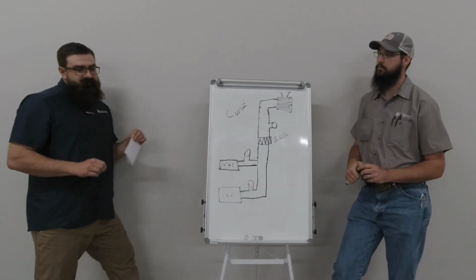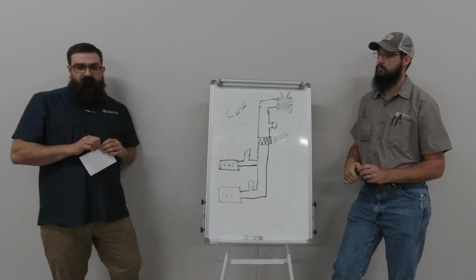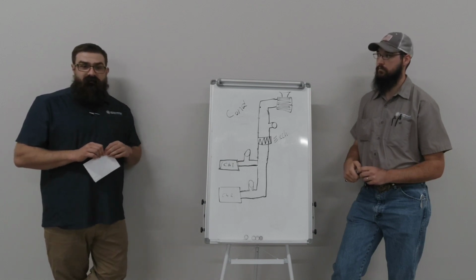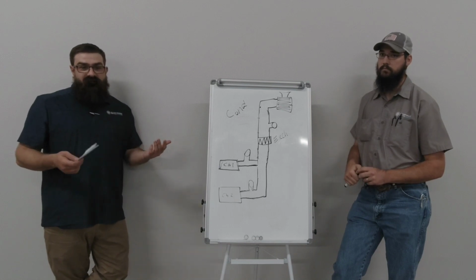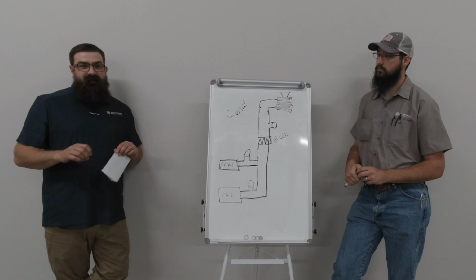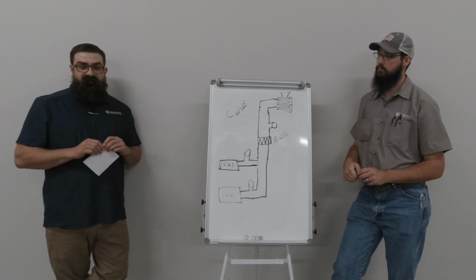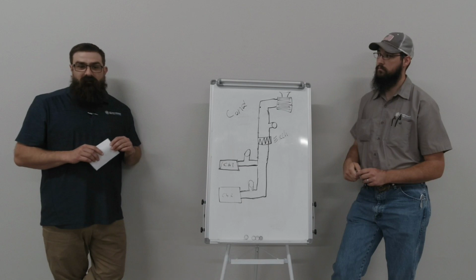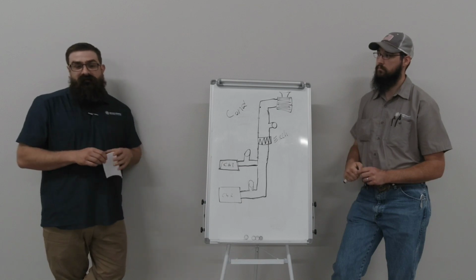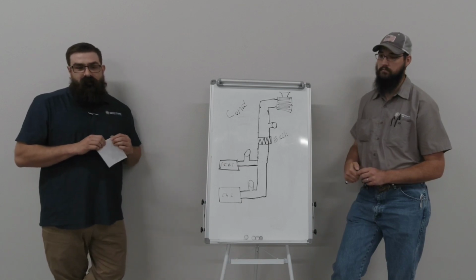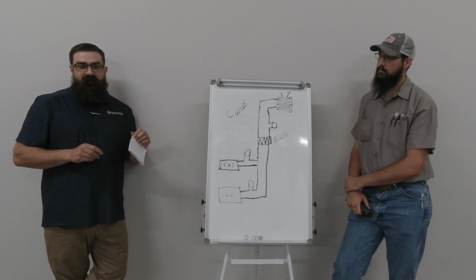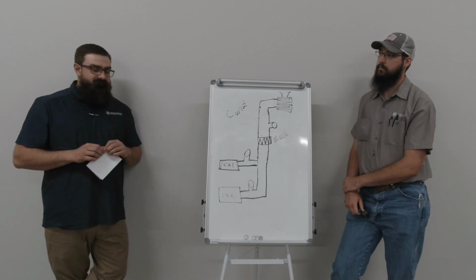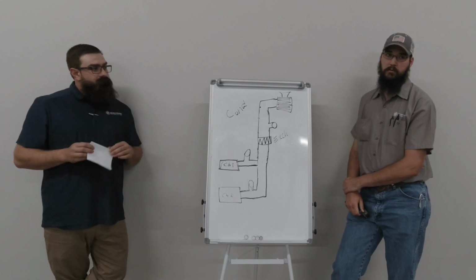The cool thing about heat exchangers is it lets you have a closed loop system on your expensive equipment and an open loop on your cheaper equipment. And as long as you keep your heat exchanger serviced, it's less likely that you are going to damage your expensive equipment from chemical problems and things like that, because you have a closed loop system that you can easily maintain. But you just got to make sure that you clean out your heat exchangers regularly because they get funky fast on an open loop system. Well, that's where chemical treatment becomes abundantly critical.